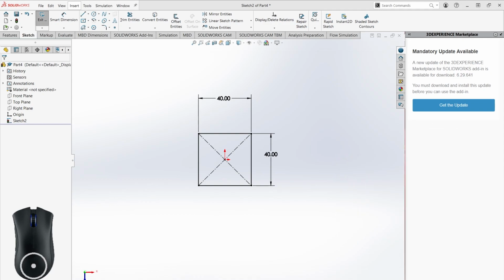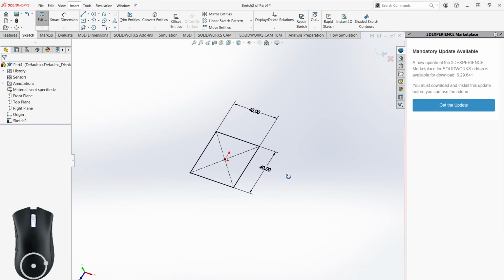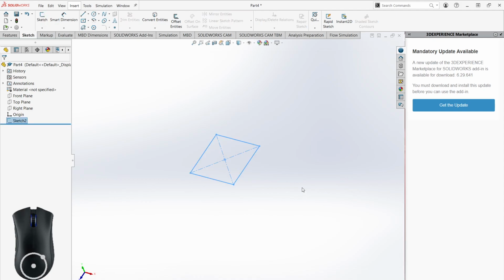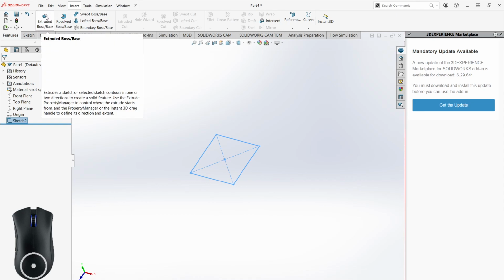Today we'll be talking about extrudes and cuts, which is the next step after creating a sketch. So you see, I've made this sketch here, I've made this box, and I'm going to click this, which is the exit the sketch, right? We haven't talked about this yet. I'm going to exit the sketch, and see it becomes blue. And when it becomes blue, that means I can come over to this features tab. I can click something here, right? So I'm going to click extruded boss / face.